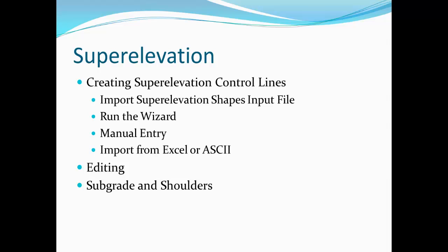With respect to subgrade and shoulder transitions, I have had little luck getting the shoulder rollover locks to match the MDOT method for superelevating the shoulder components. Typically for shoulders and subgrade, I create a single superelevation control line specifically for the shoulder and/or the subbase and apply them to template points in the point control dialog manually. So let's pop out to Power Geopack and take a look at the superelevation dialog in more detail.